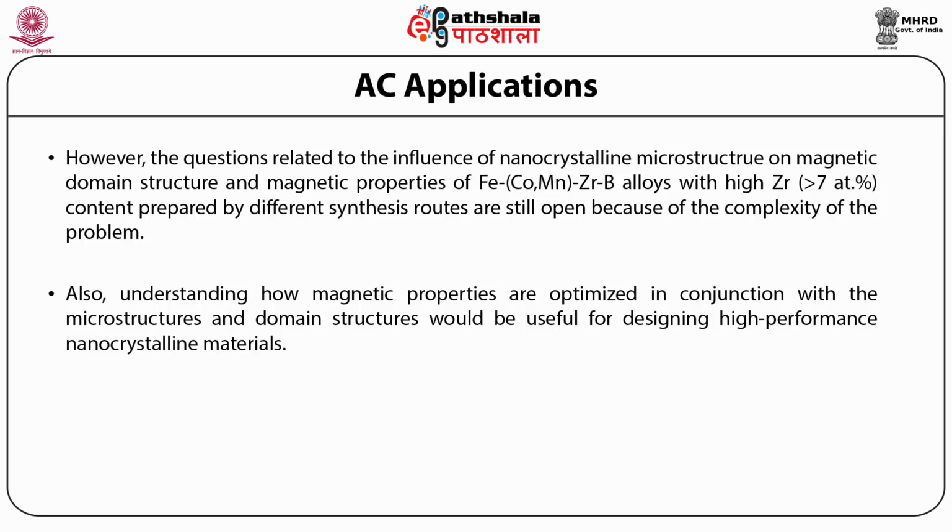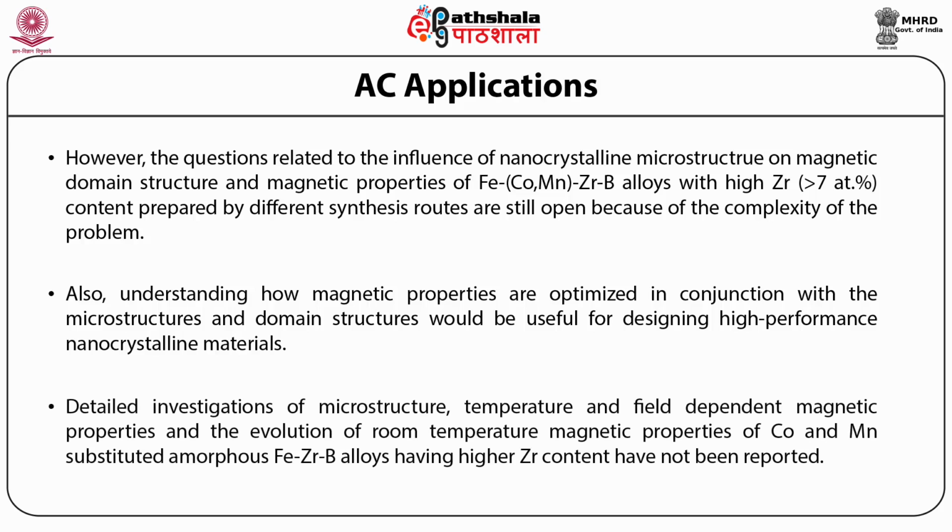high performance nanocrystalline materials. Detailed investigations of microstructure, temperature and field dependent magnetic properties and the evolution of room temperature magnetic properties of cobalt and manganese substituted amorphous iron zirconium boron alloys having high zirconium content have not been reported. Hence, investigating the influence of additive elements such as boron, cobalt and manganese in iron zirconium alloy powders and ribbons prepared by mechanical alloying and melt spinning techniques is important.